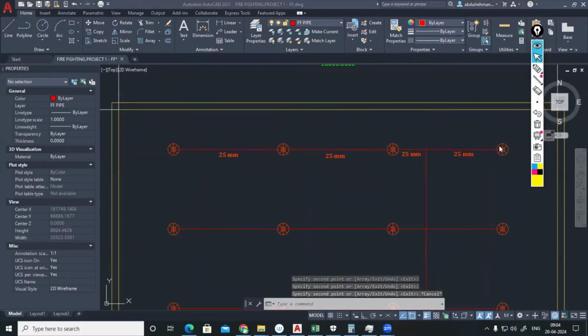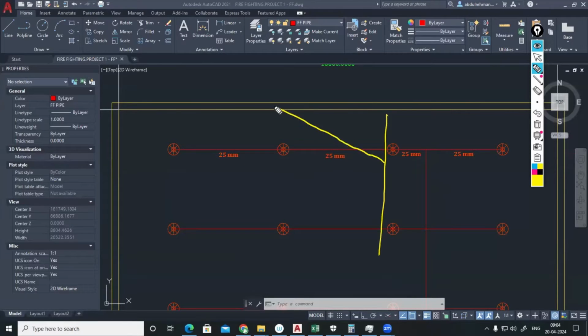Anyhow, for this building, we will have a vertical pipe. That vertical pipe is called the riser. From the riser, we will have this pipe. From the riser, for each floor, we will take a branch. This branch is called a cross main. When we take the cross main to each branch, sometimes we might require 1 cross main, sometimes more.